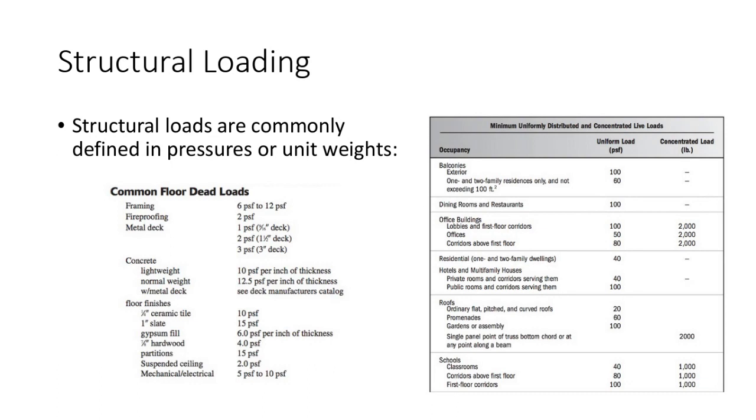So when we discussed influence lines, we had delineated this difference between dead loads and live loads. And we said that dead loads are basically permanent. They're stationary loads. They're always there. And the live loads are transient. They move around. Well, I want to sort of give you an alternative view of those definitions. That isn't wrong, but it's sort of a different way of looking at it.